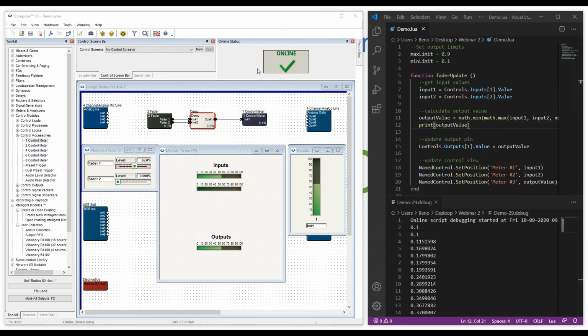That's a good question. You do not need it connected to the control port other than, let me phrase this. Assuming the Dante module does its communication over its Dante port, then you would just need to have access to it. Yes, you need to be able to have the Radius send its control signals out the proper port.